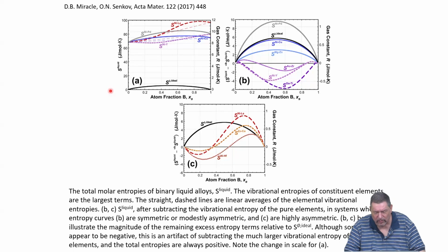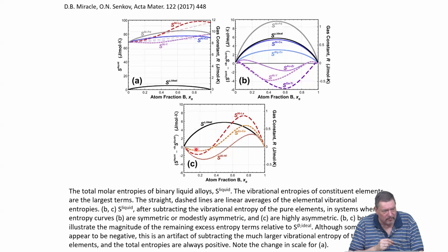And they could also depend a lot on where you are in the phase diagram, as shown here. So you could get very strongly asymmetric courses of these entropy functions, which means that your mixing entropy, which you calculate in this ideal way, might be dominant in one case and insignificant in other cases in the same binary system.